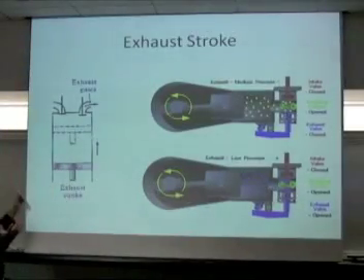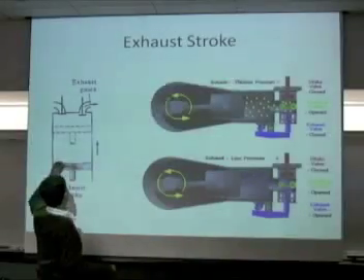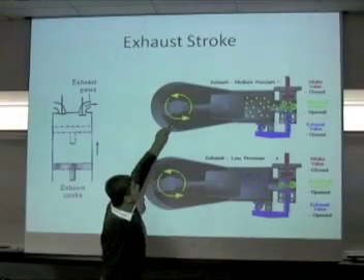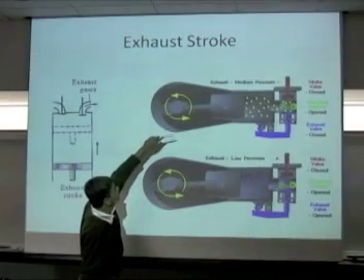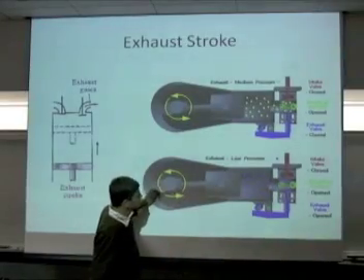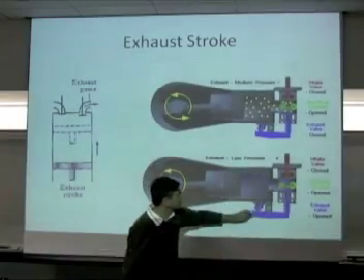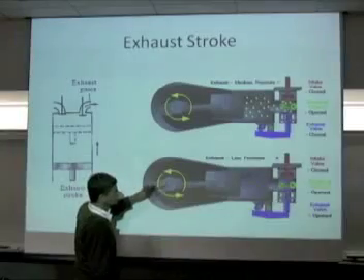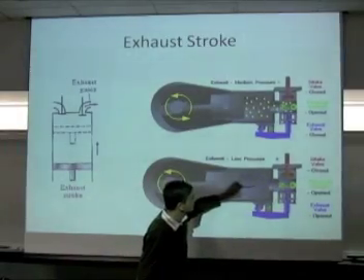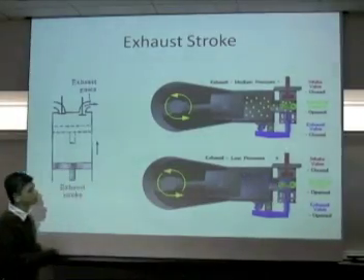At this point, the air doesn't have anywhere to expand further because the piston has reached the bottom, and the crankshaft has completed a full rotation. It has nowhere to go, and it starts turning back. The air starts getting pushed out, and because of the cam connections to the crankshaft, the exhaust valve opens, and the spent air-fuel mixture comes out and leads through the exhaust valve.